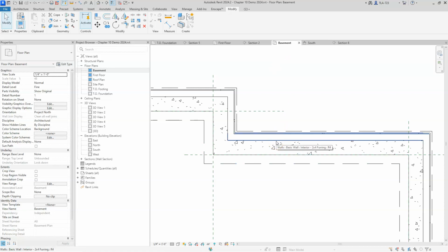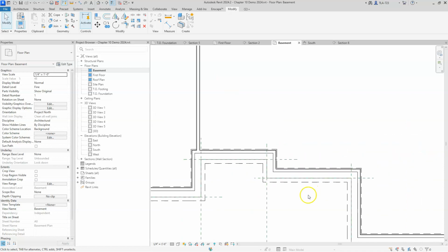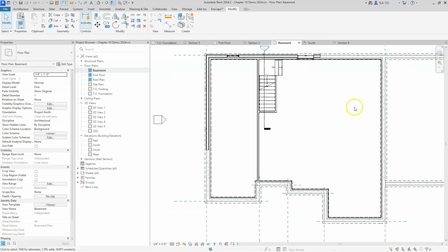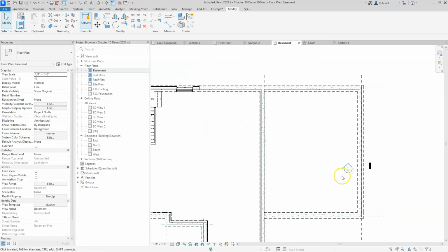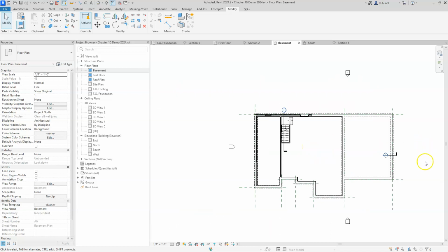Okay, so think back to the wall sections that you've drawn in the past, where that foundation wall comes in and sits right on the footing, and then the floor is poured over the top of that footing right up to the foundation wall, right? So that foundation wall essentially becomes the form for the basement floor. Let's go ahead and make one. So we're just going to build it in this area, this whole entire area. It will not be in this area because we've already got a floor there 4 feet up in the garage.